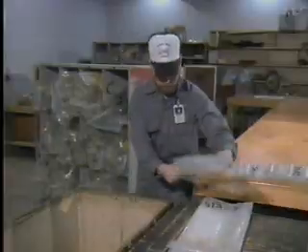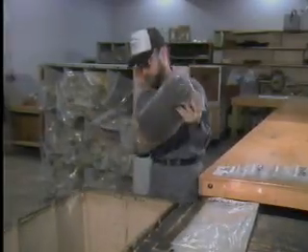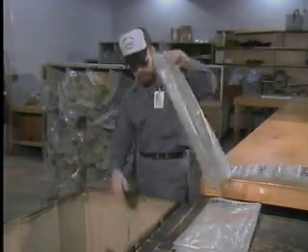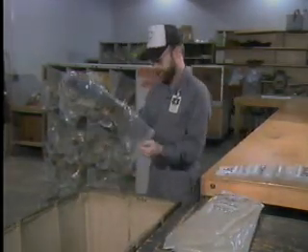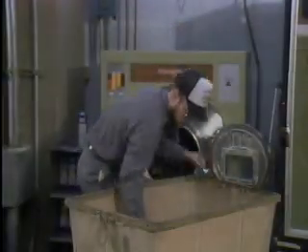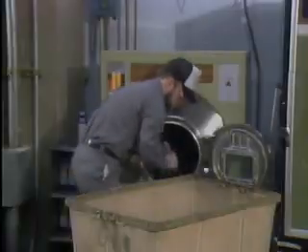In many companies, insulating gear is sent to a central location for testing. Here, a technician is getting ready to test a group of gloves. Before the gloves are tested, they are washed with a mild soap to remove dirt or other conductive materials that might have accumulated on them.